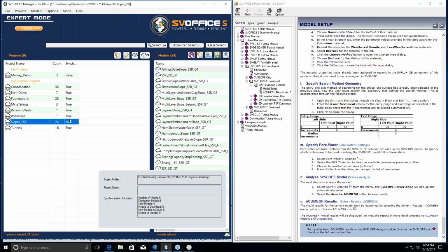And you have to also make sure that your algorithm is fine enough to detect the critical slip surface at that particular time step. So you might have to increase the number of trials on any particular step. We're making it run faster and reducing the number of trials just to get through it in the tutorial. But if you increase the number of steps with the pore water pressures and the number of trial slip surfaces, your trend gets smoother and better in this model. So that hopefully answers your question there.